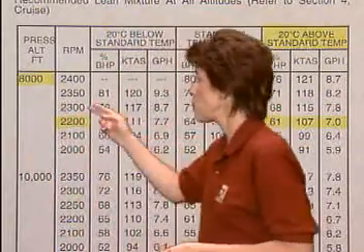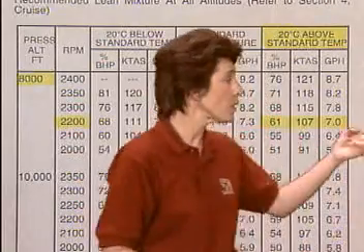Now, the next step is completely up to you. Can you imagine? You actually get to make your very own decisions. Choose one of the variables along a horizontal line, like 2,200 RPM, and accept the values of the other three. There are reasons why you might select any one of the four variables. Some examples might make that clearer. Suppose you'd like to keep the cabin noise to a minimum for your passengers' comfort, but you'd also like a reasonable speed too. In this case, you could compromise on 2,200 RPM. As you can see, this yields 61% power, 107 knots, while burning 7 gallons of fuel per hour.